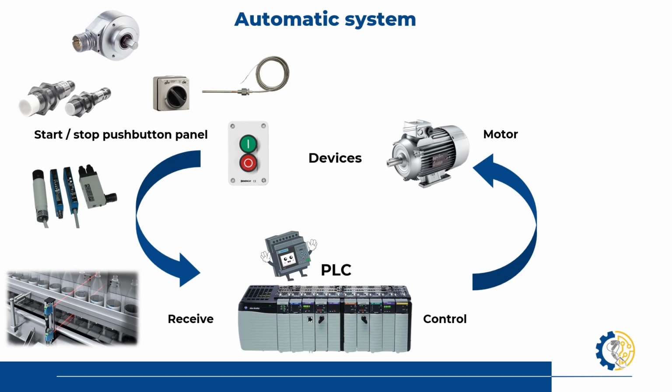We have, for those of you who don't know, an encoder. The encoder is coupled directly to our shaft. And depending on how many spins, we are able to know either the velocity or the position.